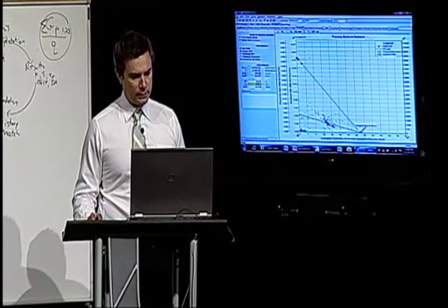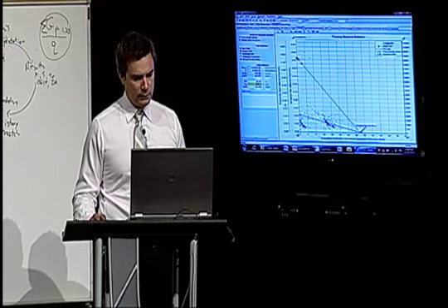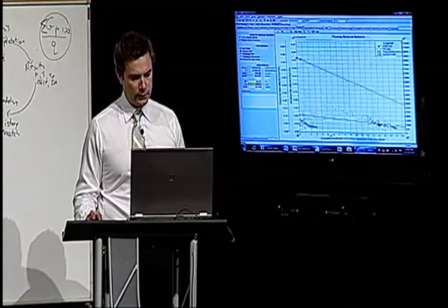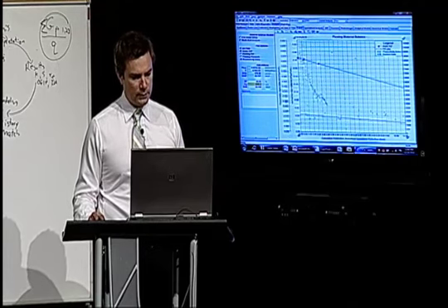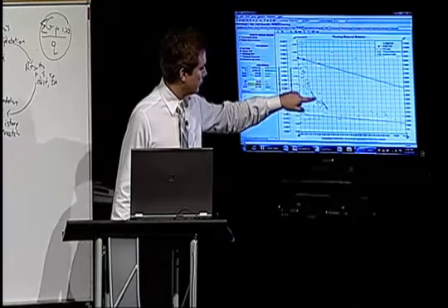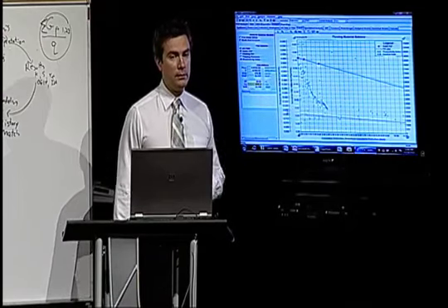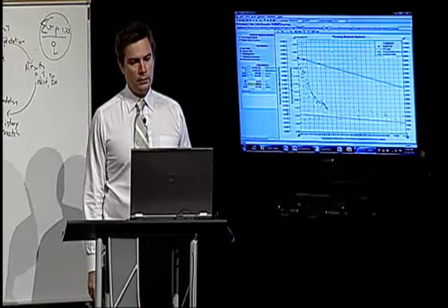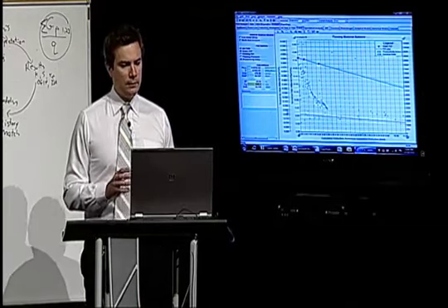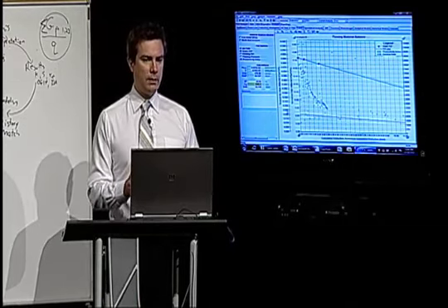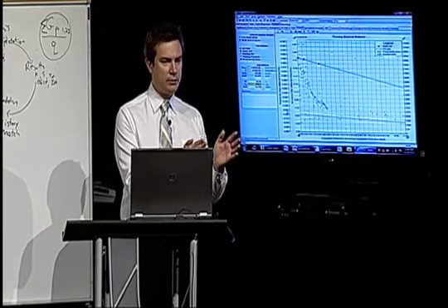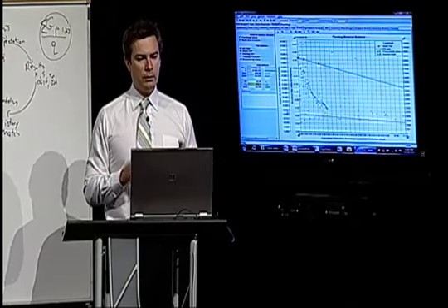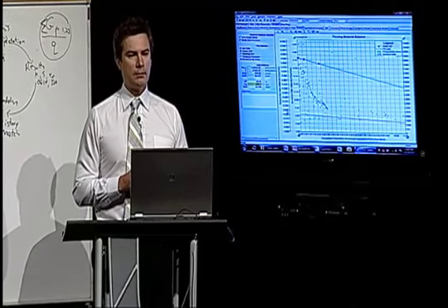If we now look at the productivity index of this one, we can see very clearly that the productivity index is a strongly decreasing function of time if we model it with the static pressures. Okay, so our interpretations vary depending on whether we believe the static pressures or the flowing pressures. Well, in this sort of situation, you have to believe the static pressures.